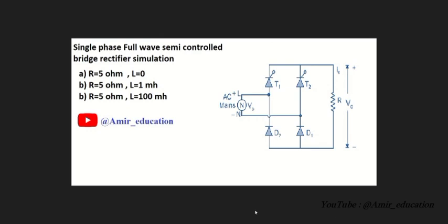It's Amir Hossein and today I'm gonna simulate a single phase full wave semi-controlled bridge rectifier. The only difference between a full wave semi-controlled rectifier and a full wave full controlled rectifier is that we substituted the two thyristors with two diodes.